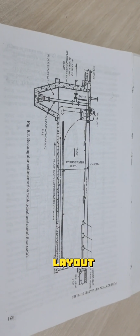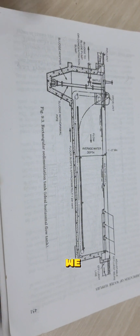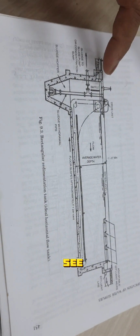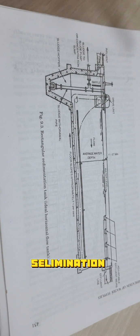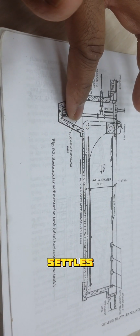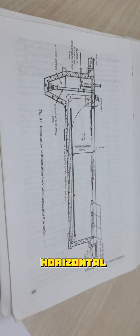Now this is a typical layout of the rectangular tank, or you can say a horizontal flow tank, where we have water coming in. This is called the influent. These are the baffle walls. Baffle walls basically restrict the flow of the water. You can say they slow down the flow of the water so that there is proper sedimentation, or settling of the particles. This is my water level, and these are my sludge hoppers, and here the sludge settles down. This is my effluent line from where the water will be going out. So this is my typical layout of the horizontal flow tank.